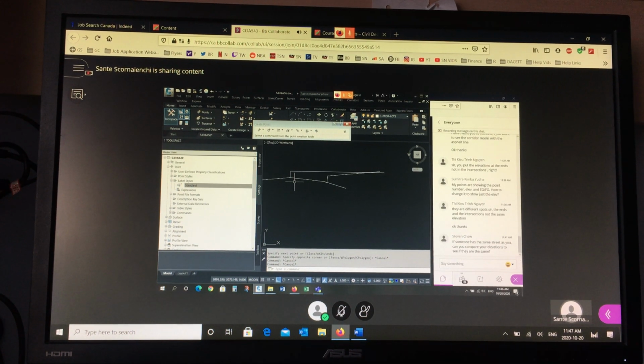And some municipalities actually write that into your standard. If you're going to propose a new subdivision, the street line along the existing rural road must be 0.3 above the existing center. That's usually the rule. And if that rule's not in effect, it usually, as a rule of thumb, works everywhere. Okay? So here's how you do that.